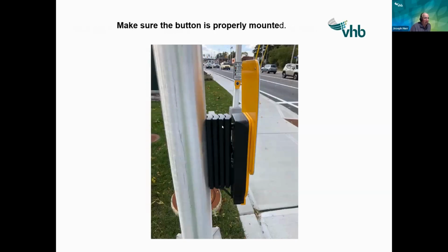Next, you want to make sure that the brackets, the standoff brackets, are meant for that application. This is not meant for that application. They got 4 shims here. And also, if you notice on the bottom, they have a wire that comes in on the bottom that's exposed. So you have to make sure that you have the right equipment for the right application.